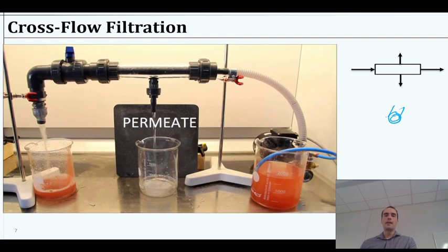In this case it appears that we're feeding from here. So we've got this feed, this dirty water. It's being pulled by this blue pipe into this pump. And then from the pump, it's being pressurized into here. So we're applying a pressure, and inside this little chamber here is the membrane.